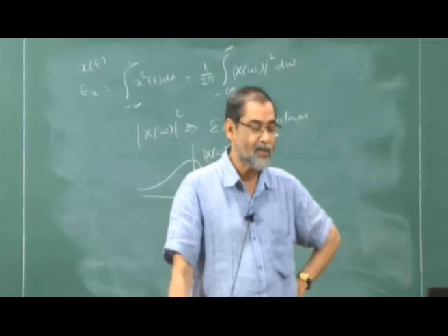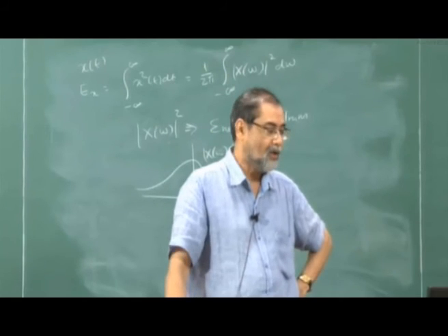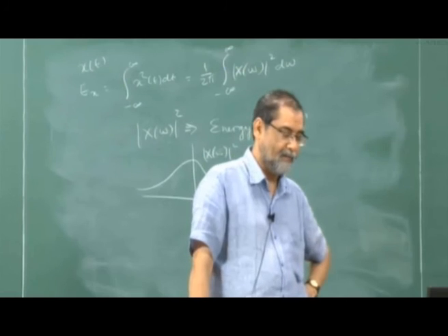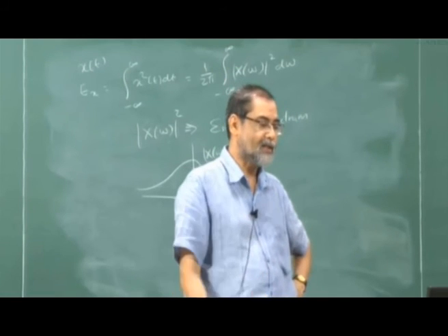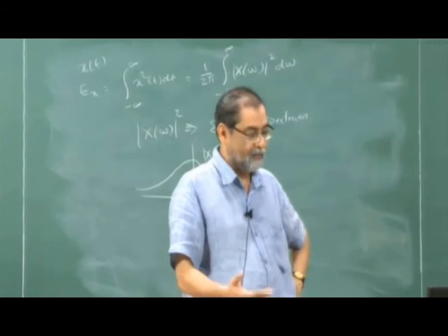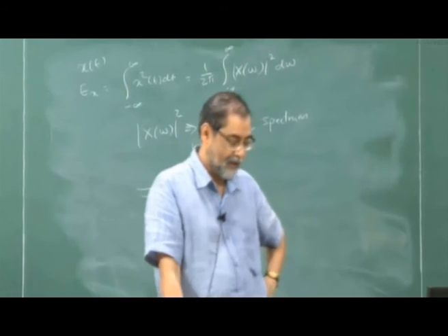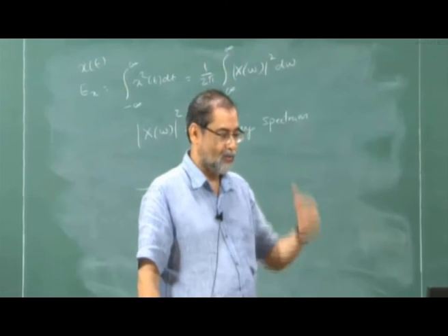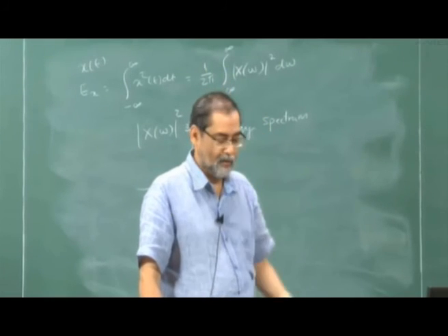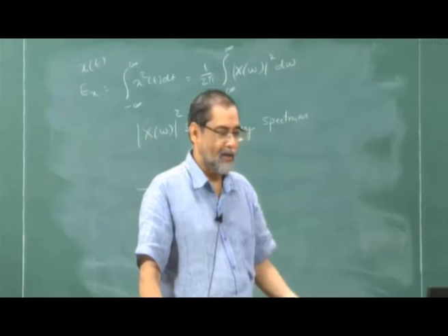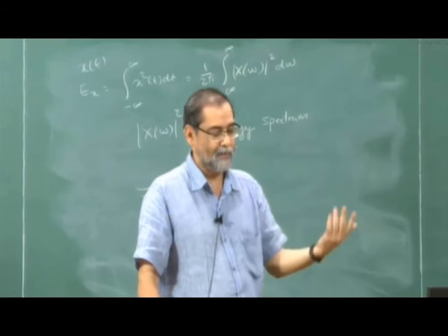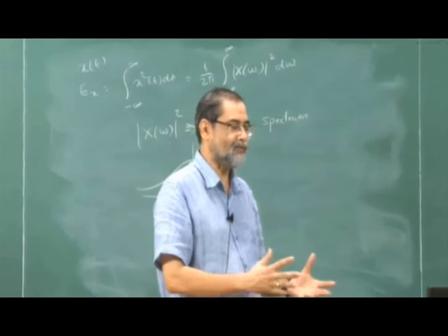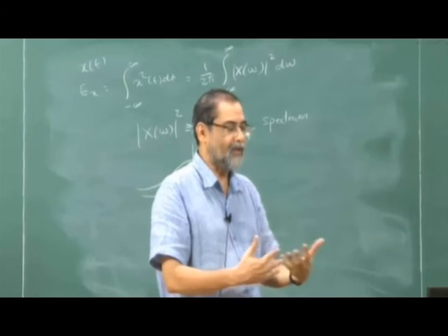So it's a more general transformation, and what is true for Fourier transform is also true for Laplace transform. Many of the results come out even easier in Laplace transform. You could analyze in the frequency domain with the j omega axis, or in the complex frequency domain with the sigma plus j omega axis. So Fourier transform and Laplace transform are very close to each other.